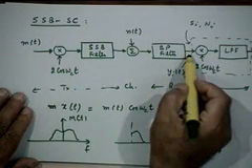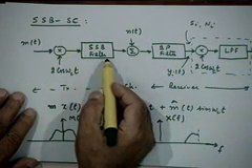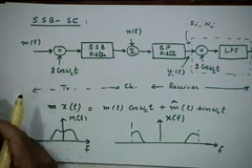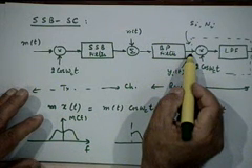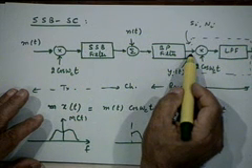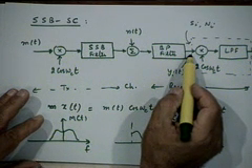What is the signal that is coming here? It is a transmitted signal, which is the SSB signal, which has its representation in terms of the Hilbert transform, plus the noise. And what kind of noise is present here? Band pass noise, narrow band noise, which again one can write in quadrature form, right.